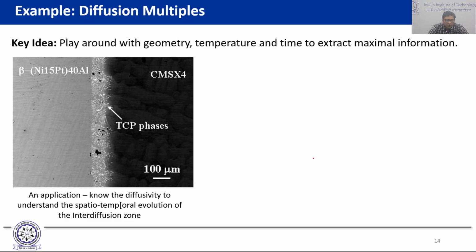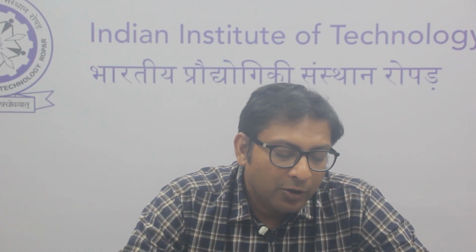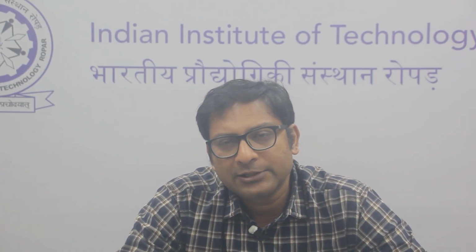So for instance, if you are looking at the jet engines, the turbine blades are often made out of superalloys, single crystal superalloys. So in this case, we are looking at CMSX4, and then what you do is on top of the superalloy, you deposit a bond coat which is supposed to protect the alloy from oxidation. Now the bond coat has one composition, the superalloy has another composition.